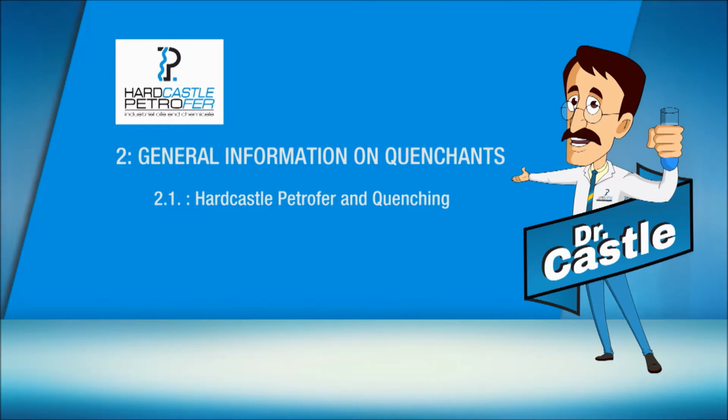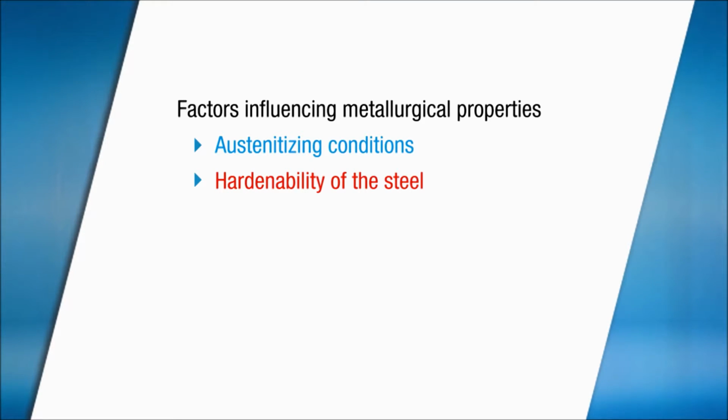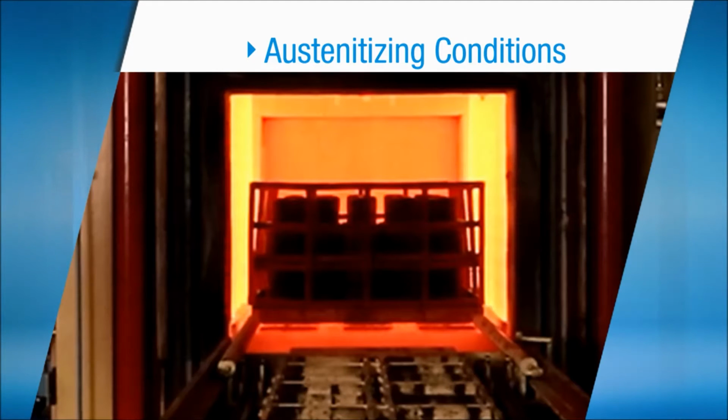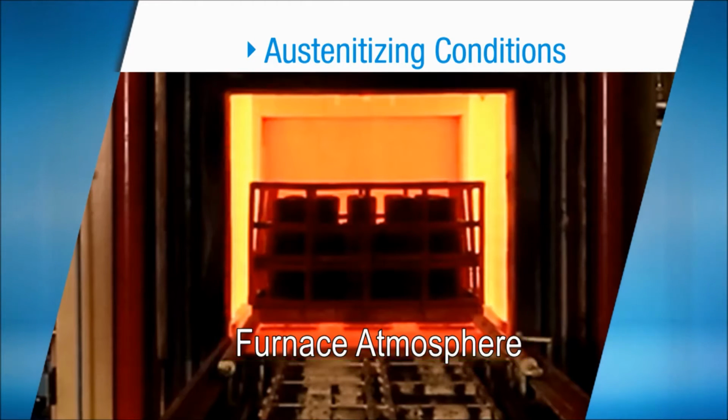Well, now we begin with the first subtopic under General Information on Quenchants, Hardcastle Petrofer and quenching. The metallurgical properties of heat-treated steel components are primarily dependent on the following factors: austenitizing conditions, hardenability of the steel, and quenching process used. To begin with austenitizing conditions, the austenitizing conditions like hardening temperature, furnace atmosphere.